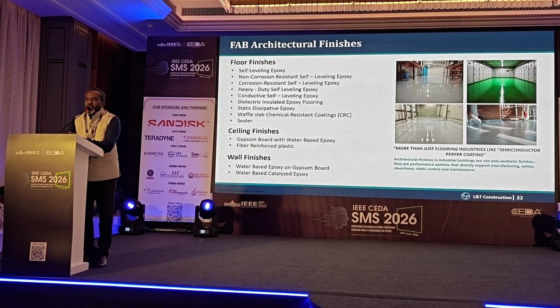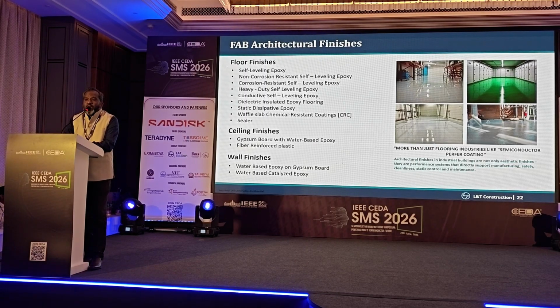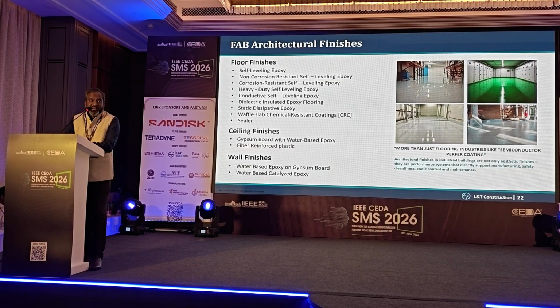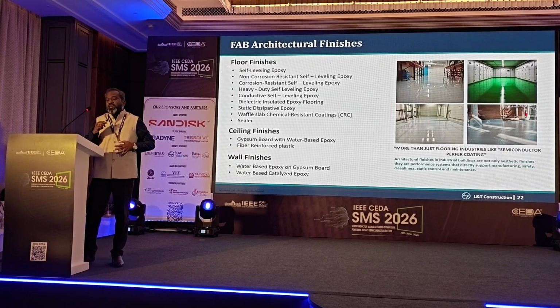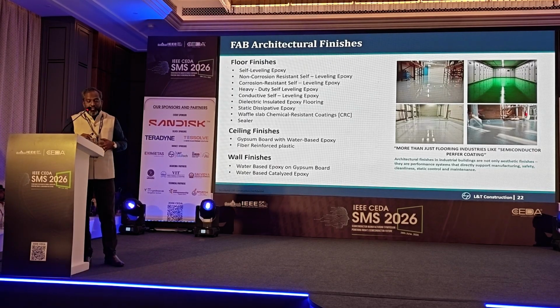And this is about clean room, and then you will have a lot of concrete that is to be protected, right? Concrete generates dust, and I cannot afford to have dust, so there are a lot of special coatings that are required, and especially in L30, this needs to be a corrosion resistant coating.